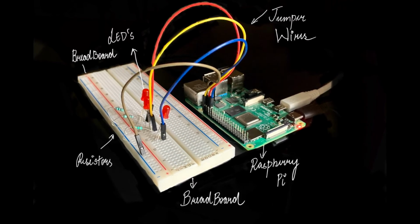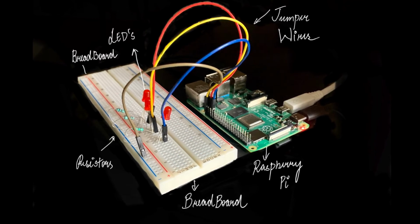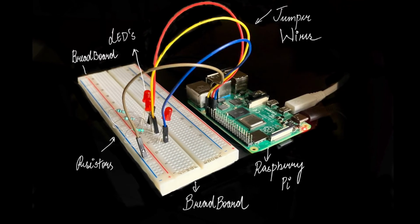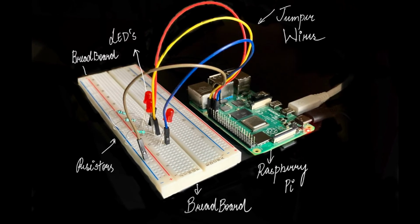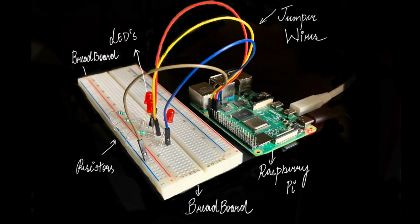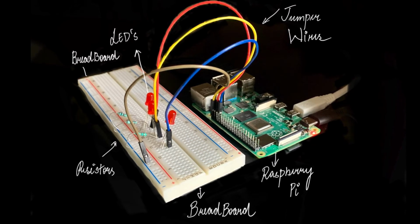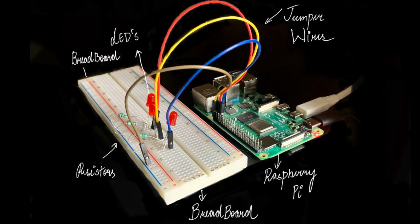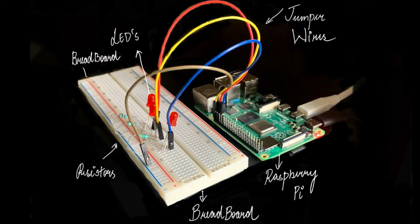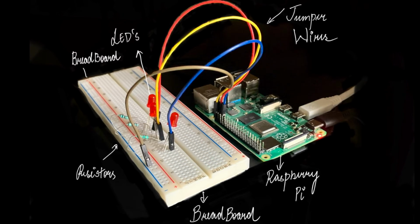Jumper wire number one is connected with the ground, which is at pin 39. Then we have an LED connected with pin 40, or GPIO pin 21. Then we have another LED which is connected with pin 37, or GPIO pin 26. And then we have the third LED, which is the last one, at pin 35 and GPIO 19. So these are the connections, and this is the whole setup. Next, we are going to see the code part.